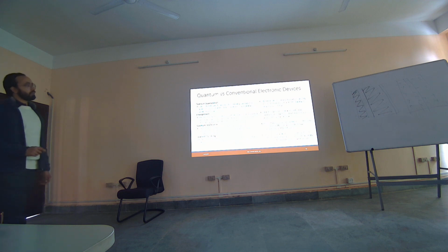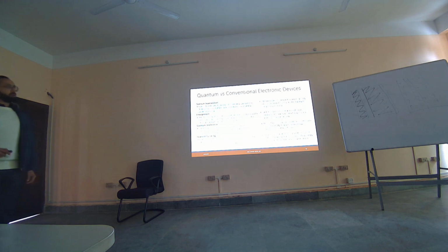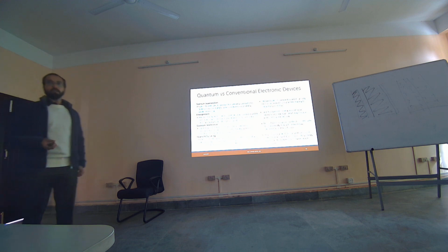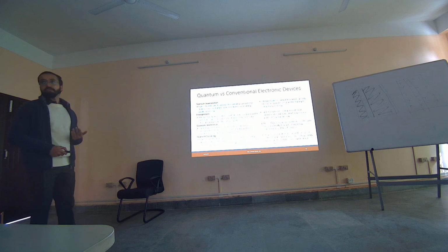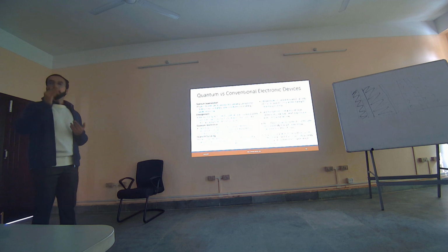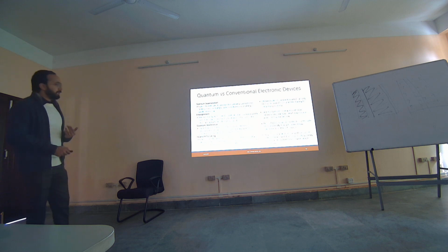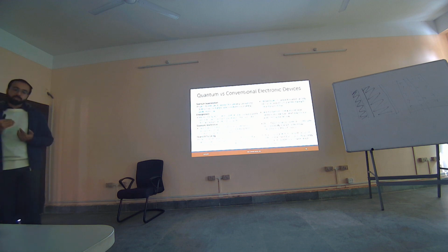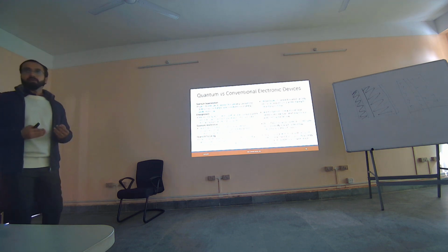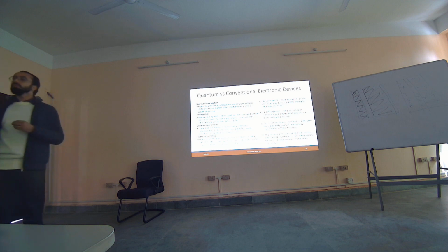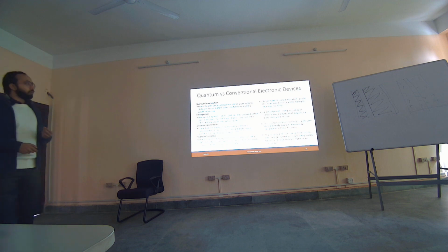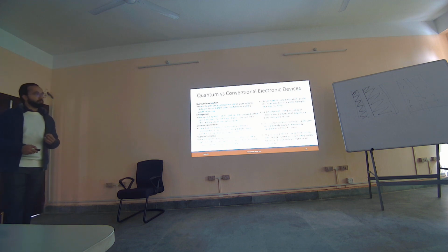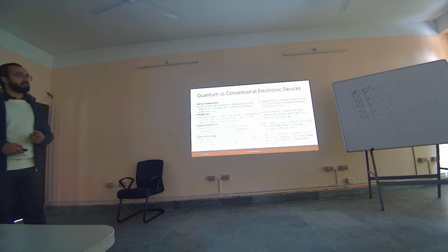Third, quantum devices use interference, but interference cannot be used by classical devices. Fourth, quantum devices harness tunneling. If I take the simple example of a GMR and a TMR, GMR is a classical device. It doesn't use tunneling; it uses simple conductivity across a metal layer. In TMR, I am using tunneling: my electrons are tunneling through the insulating layer. That gives me, as I told you, a big advantage in terms of noise immunity, and it gives me higher sensitivity. So already we see how quantum effects can help us overcome the shortcomings of classical devices.